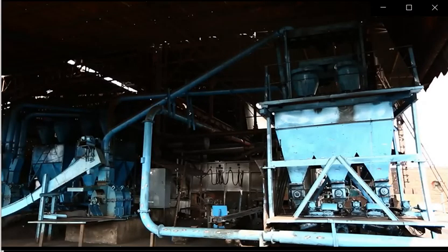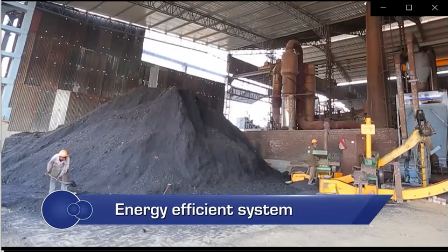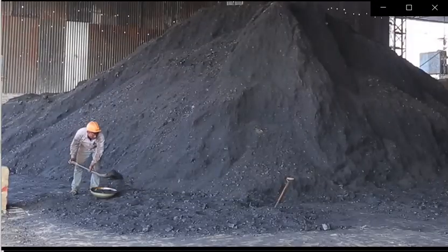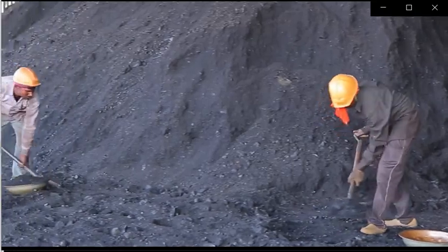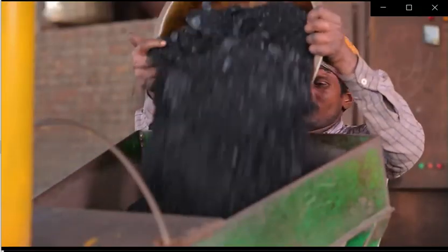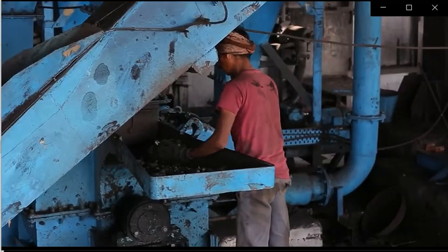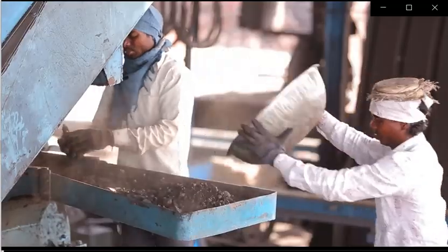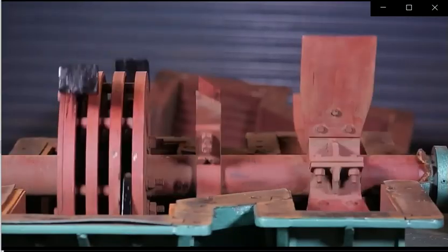The energy-efficient alternative to using pulverized coal as fuel starts with the procurement of good quality coal. Coal with high calorific value and low ash content, for example Assam coal, is the most ideally suited for use as pulverized coal. The next step is to process or pulverize the coal into the desired fineness consistently. To do so, certain modifications in the pulverizer are required.